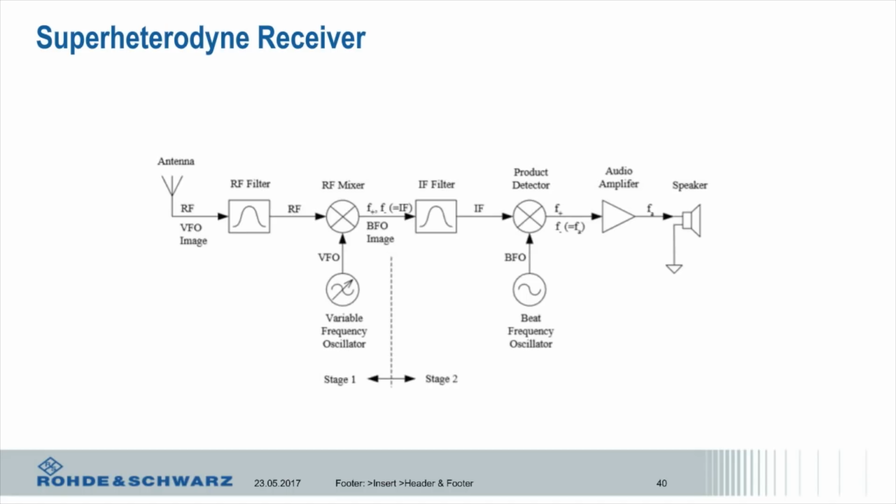But it's also to reject other signals coming from other things, cell phones, cars, garage door openers that I don't want. That comes to a lower frequency, which we call an IF. Then that IF signal is filtered again, and then it's going to be further reduced to a lower frequency and then processed. So in the old world, things were just audio, but obviously this would be something more like data today.